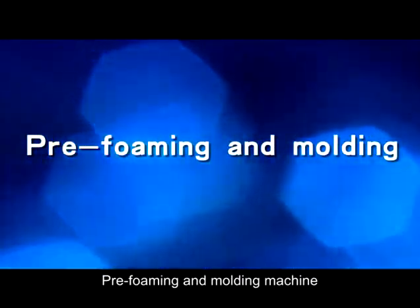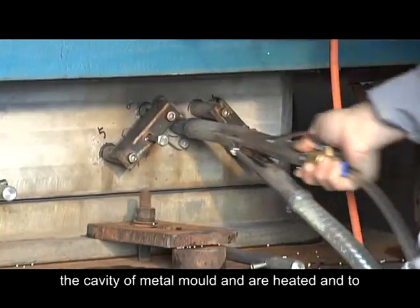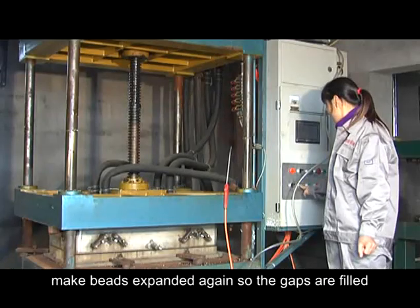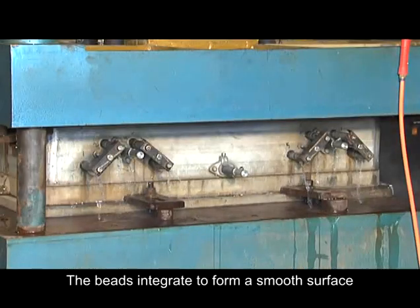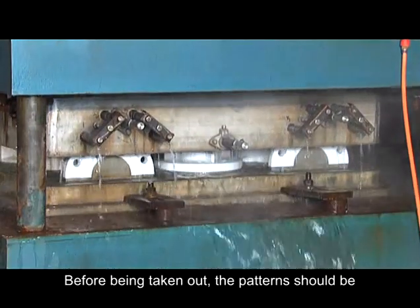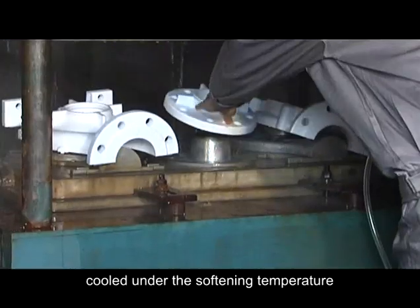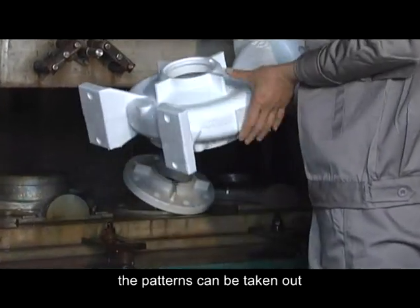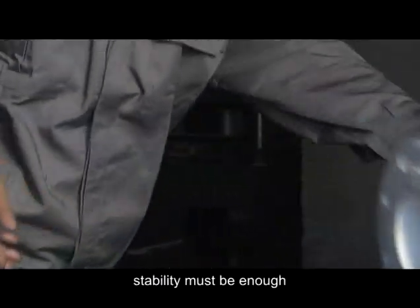Preforming and molding. The preformed and ripened beads are filled in the cavity of the metal mold. The beads will be heated and expanded again, so the gaps between beads are filled. The beads integrate to form a smooth surface, which is the pattern form. Before the patterns are taken from the cavity, the patterns should be cooled under the softening temperature. Only after the patterns are formed and hardened, they can be taken out. There should be pattern drying and dimensional stabilization for some time.